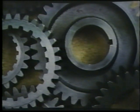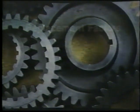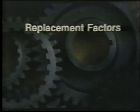Notice that the pit craters are much larger and deeper than in moderate pitting. This kind of destructive pitting can cause very serious problems. You've just seen, in destructive pitting, one example of the kind of distress sign that means the gear should be replaced. Let's pause for a moment and review the factors to consider when deciding whether to replace a certain gear or reinstall the old one.